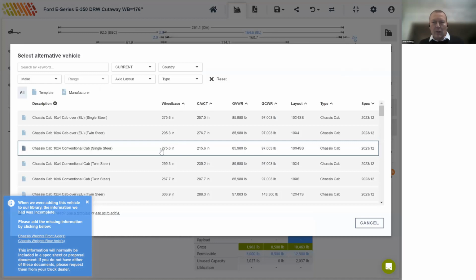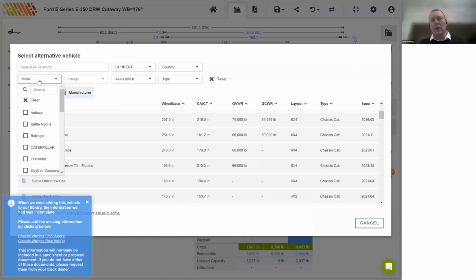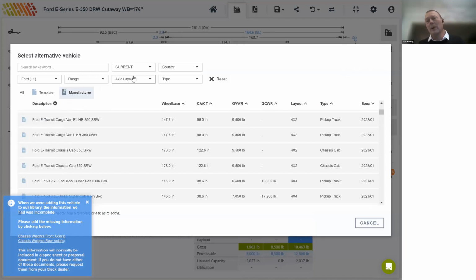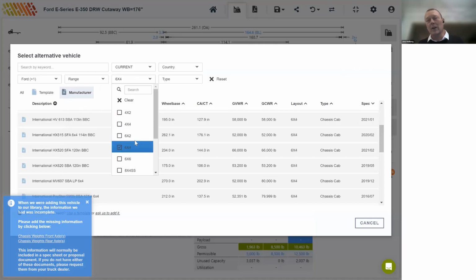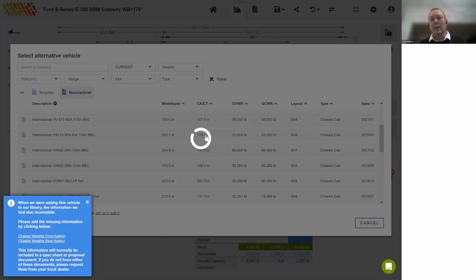The question is on each individual axle, so axles 2 and 3, whether we can split the weight over those axles. On a tandem axle set, we calculate the weight over the group, but if you were to add a pusher or tag axle, we do calculate the weight on those individual axles. But on a tandem axle, we calculate the weight on the group.